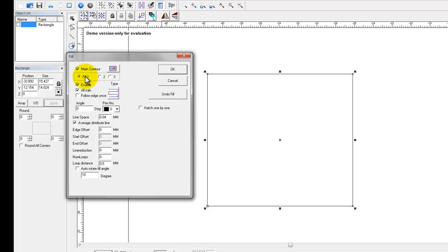In other words, if I'm trying to achieve a specific type of mark on a material, let's say what we call a black annealed mark, which is a very jet black surface mark on a piece of stainless or titanium, I'm going to use specific laser settings in order to obtain that mark. However, I also need to have the proper fill, because without the proper fill I'm not going to get the result I want. So it's very important that you have the right fill and the right combination of laser settings or parameters together in order to achieve the mark that you're after.